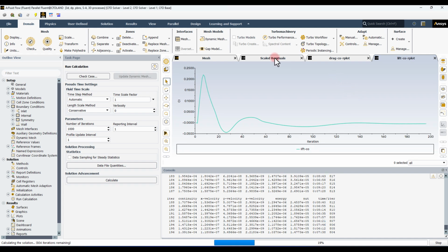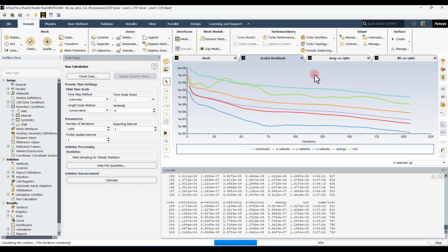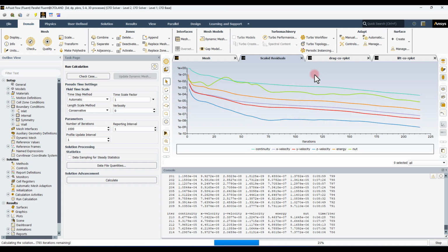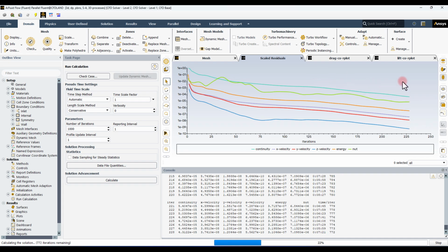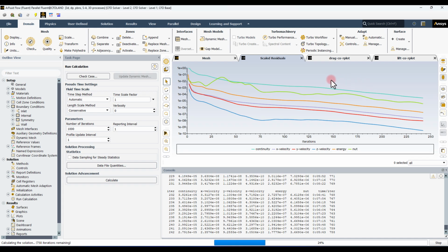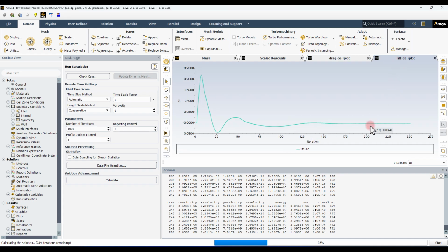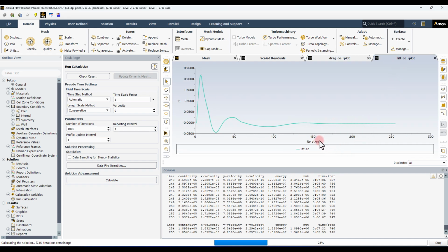Very well, so let's check the results. As you can see in here, we've got a perfect convergence, and the main reason for that would be our solver settings, but more importantly it's the structured grid. And as you already see, by considering the primary convergence criteria as residuals, the solution has stopped earlier, but we can see that it hasn't reached convergence before 140 or 150 iterations.